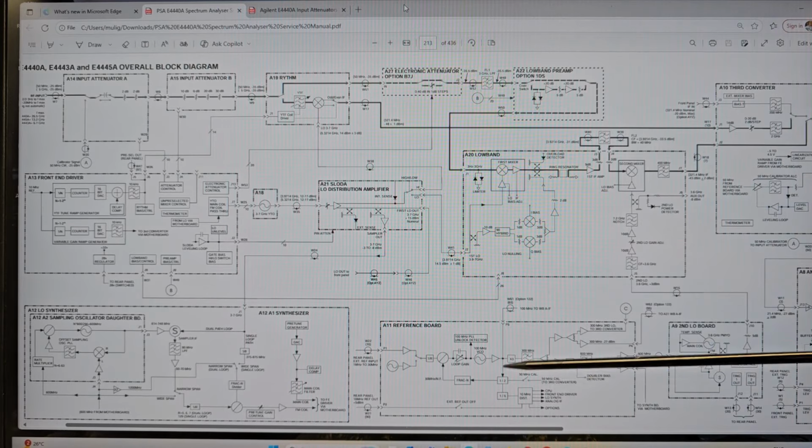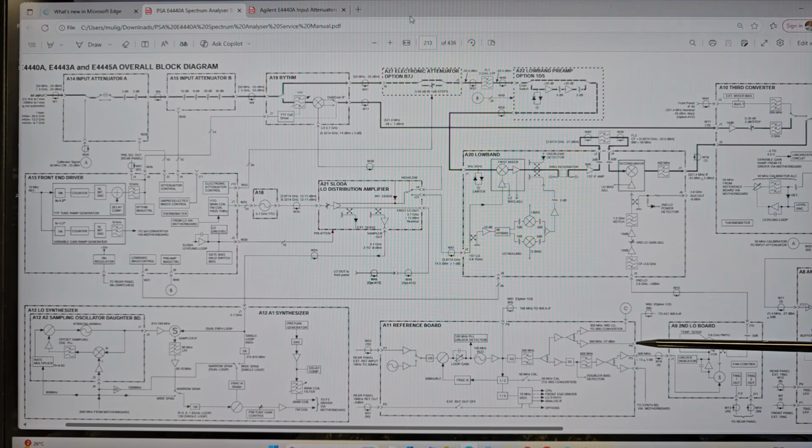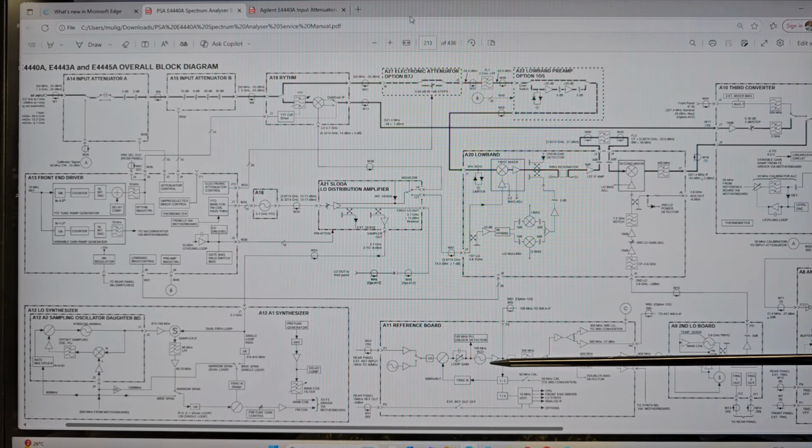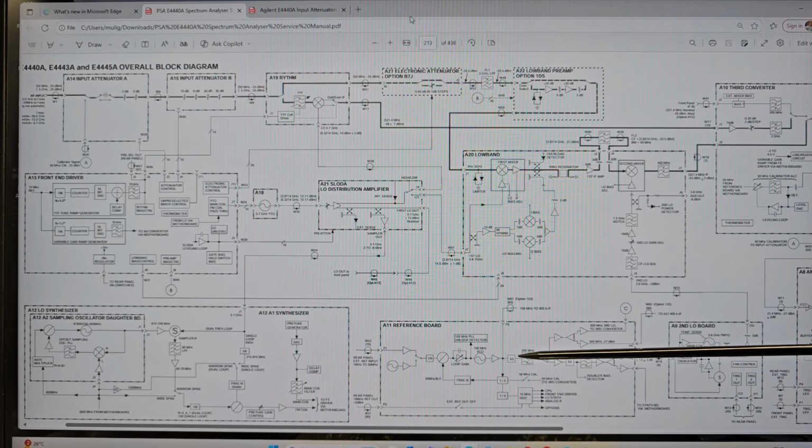If we don't have a 600, but we have the 300, then likely we have the 100 megahertz voltage controlled oscillator here. It goes into an amplifier, and then it multiplies by 3, so the third harmonic of this one is used, filtered. The third harmonic of 100 meg is the 300 meg, and then you filter it out and you have the 300 megahertz frequency.